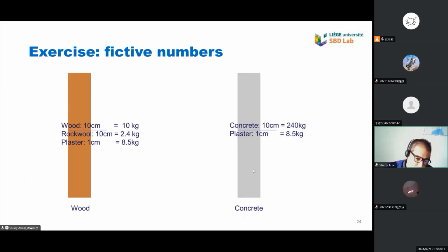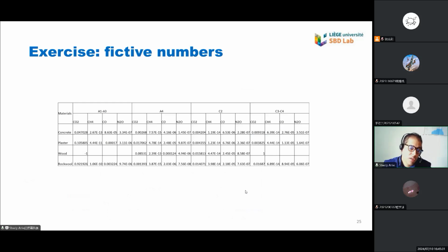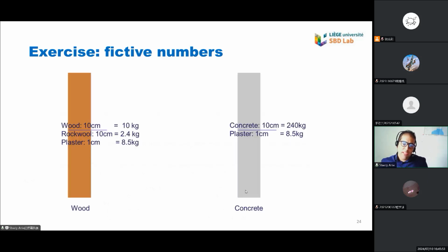And the functional unit that you must use for both calculations is CO2 equivalent, or kilograms of CO2 equivalent, of materials for wood composition and for concrete. Based on that, we can start to inform the decision making, and we use these scientific-based calculations to say which wall composition has a less negative impact environmentally on the construction.